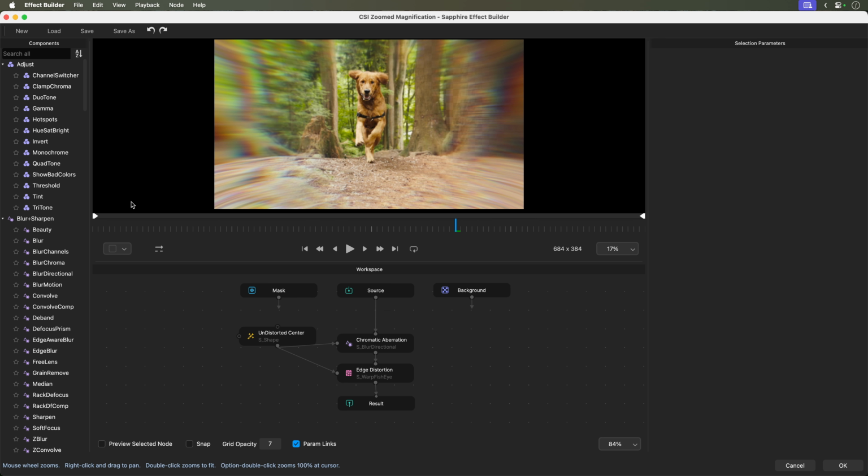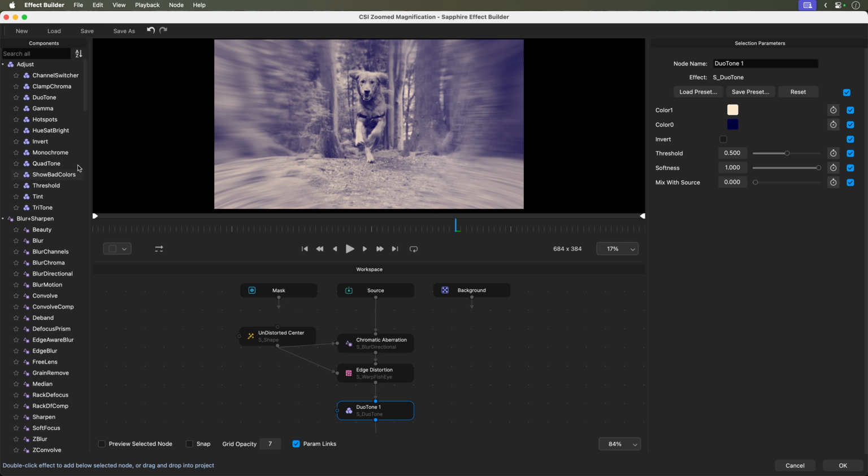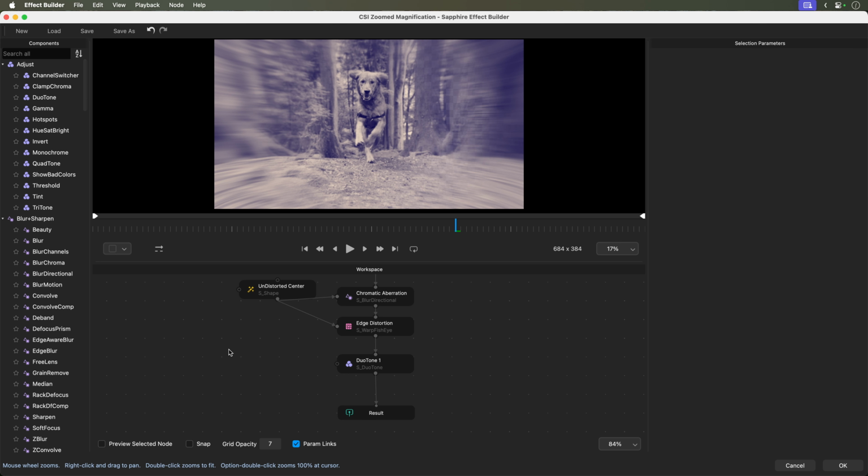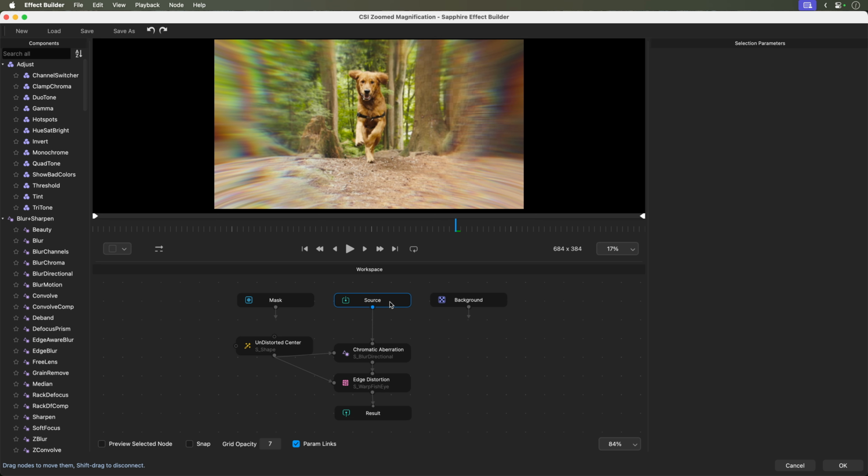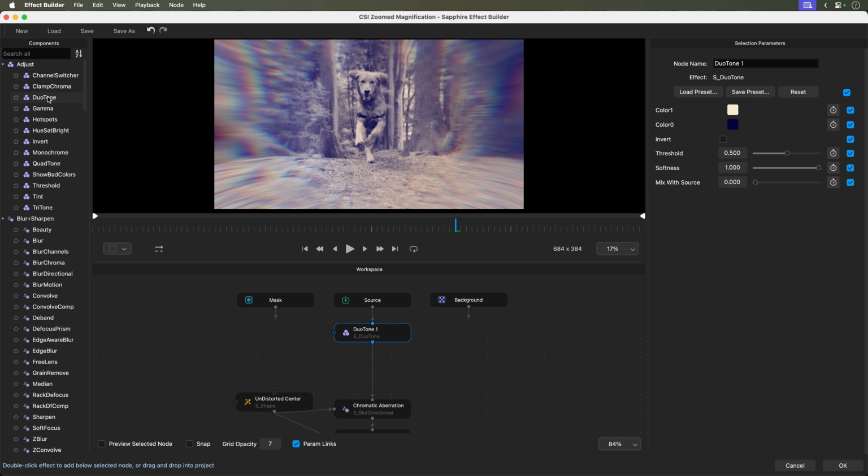Number 2, the double-click method. This is a context-sensitive operation whereby if nothing else is selected, the new filter node is inserted at the end of the node tree. Great for stacking up effects one after the next. But if you want to add a filter between connected nodes, select the node where you want the filter to come next, and then double-click on the filter.